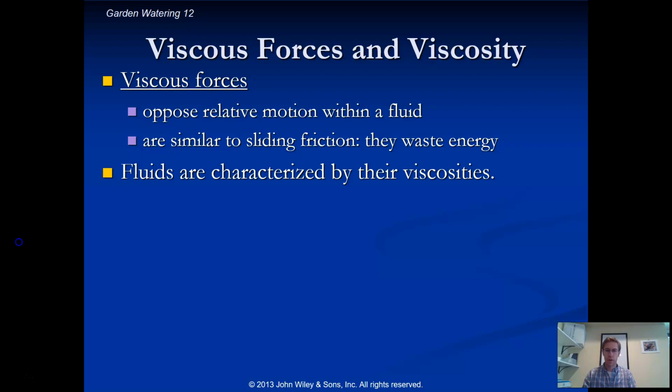either taking away pressure potential energy, or since it's moving, it's going to ultimately be taken away from the kinetic energy. And so how much that's going to happen depends on a lot of different factors. But one primary factor is what's known as the viscosity of a fluid. It's a measurement of how strong the internal friction in the fluid is. Think of it as sort of being analogous to the coefficient of friction with two surfaces. It's like a coefficient of friction, but for a fluid when it's rubbing against itself. All right, so again, this viscosity is a quantification of how strong those are.